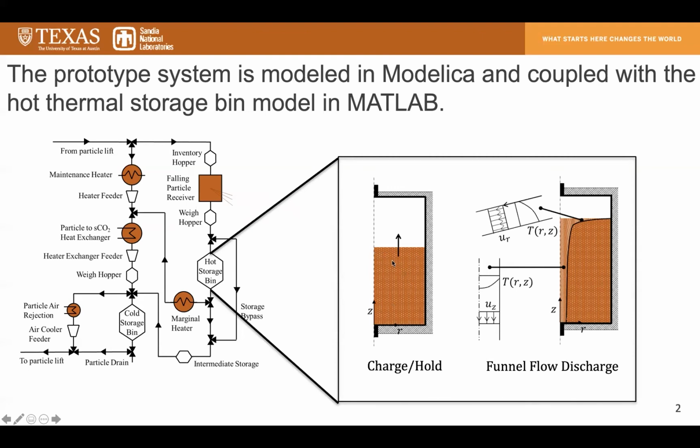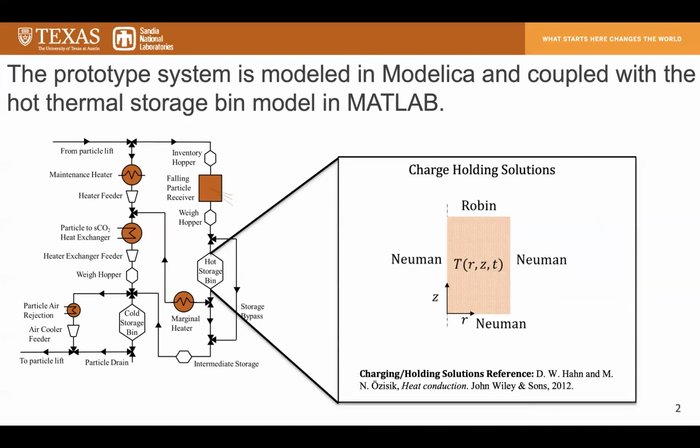For charge, we have an inlet flow rate of 9 kilograms per second, and it charges over a duration of 6 hours, and then it's held for 10 hours, and then it discharges at a rate of 5 kilograms per second over a period of 8 hours. So all of these modes have to be considered, and we need to understand how heat is being lost throughout each of those modes.